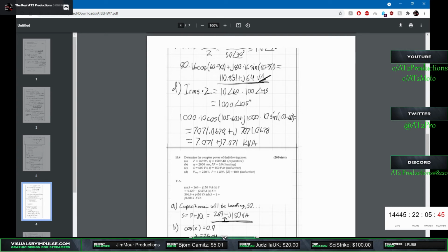So say it's a 60 hertz motor at 500 volts and the motor runs at 1800 RPM full load. You want to run the motor at 900 RPM, so you want to run it at 50% load. You're going to give it half voltage, half frequency from the VFD. Yeah, that makes sense. And you do that by how your SCRs fire.